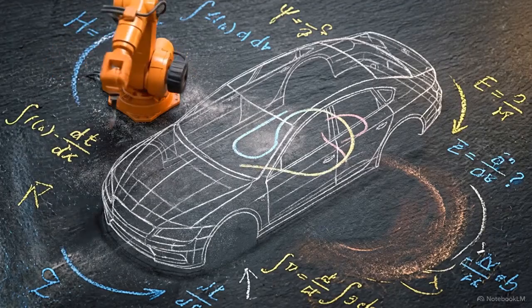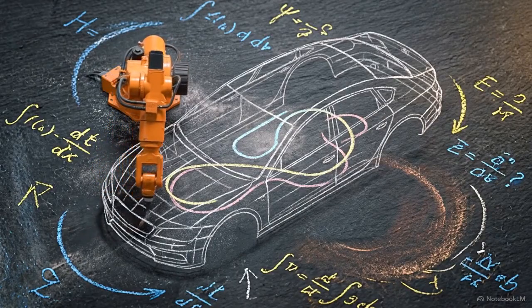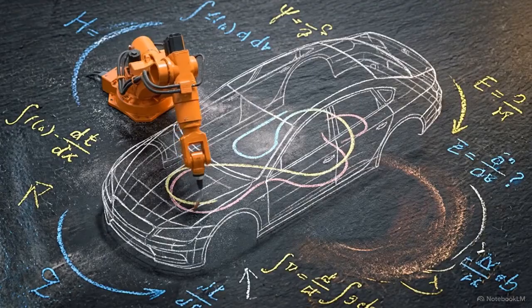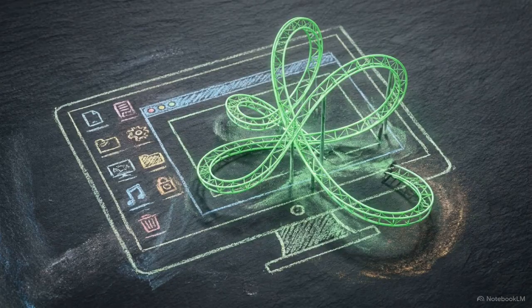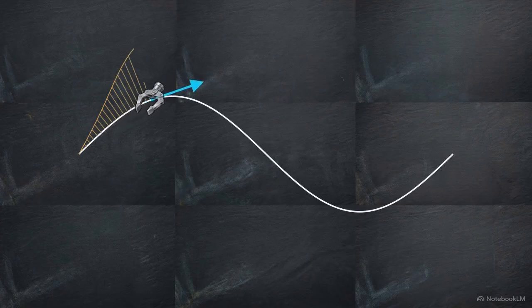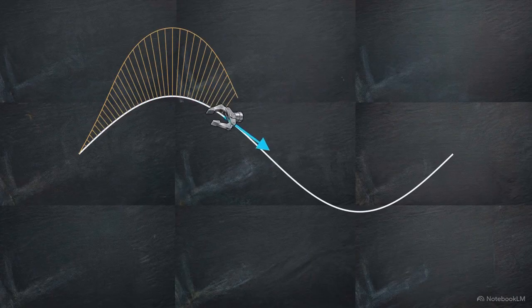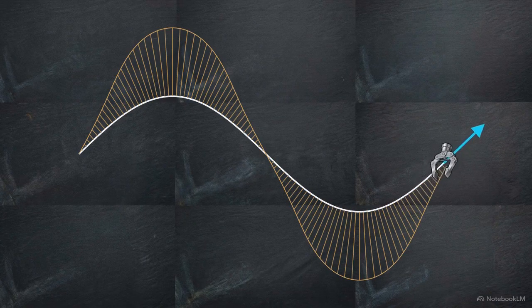These critical mathematical constraints are also central to automated control loops, where heavy physical robotic hardware navigates through exceptionally tight, complex manufacturing environments. Standard algebraic functions cannot model paths that turn back on themselves, forcing engineers to use parametric B-splines. The control loop uses the first derivative to determine the correct velocity vector, updating joint orientation in real time. The second derivative verifies C2 curvature continuity, ensuring the path geometry transitions perfectly smoothly.